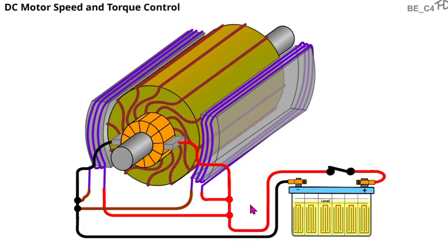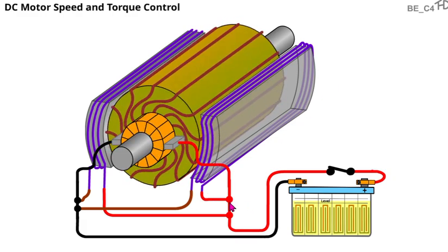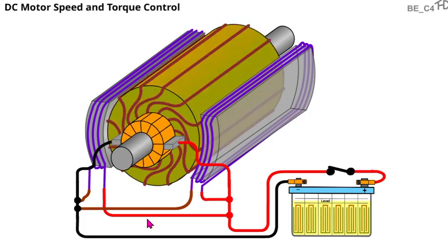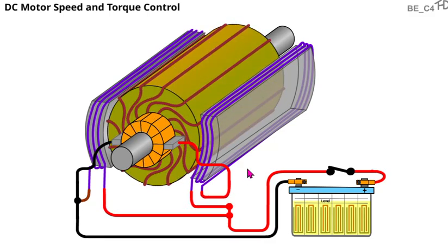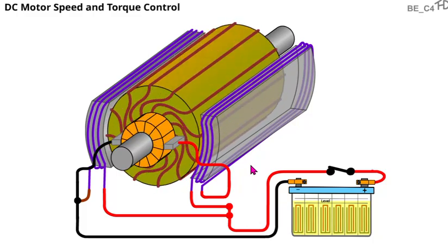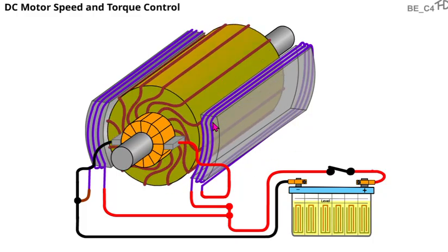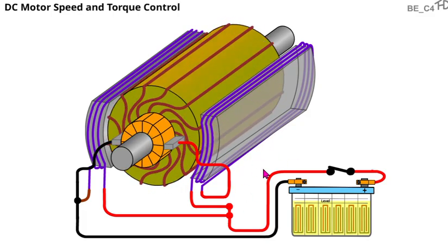And then we have the shunt type, which is just a parallel arrangement. So it's feeding separate power to the field coils and then a separate power to the armature. These are not as high torque as the series motors are. So wiper motors, window motors, things like that. And then compound. This would probably be the most popular that I'm aware of for heavy duty trucks. Very, very high torque. And depending on the exact design and wiring, they can provide varying levels of torque and power output.